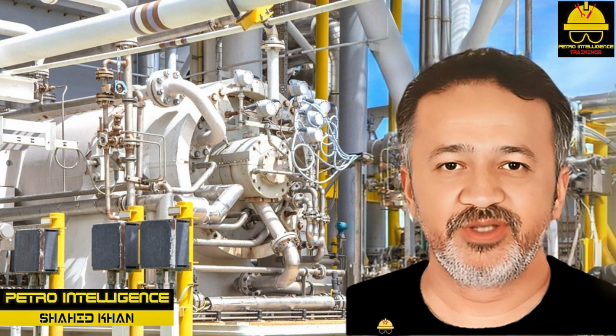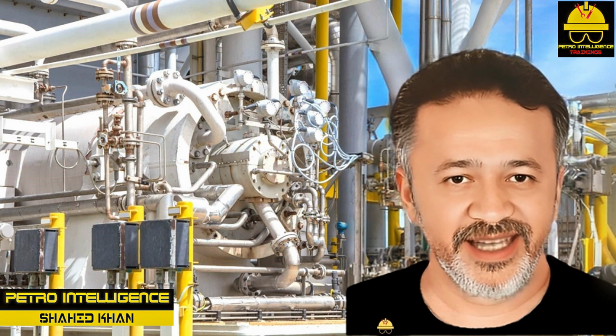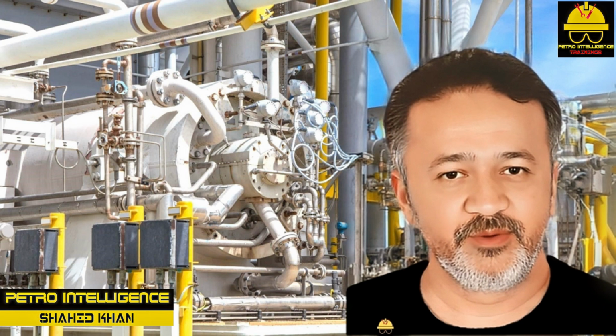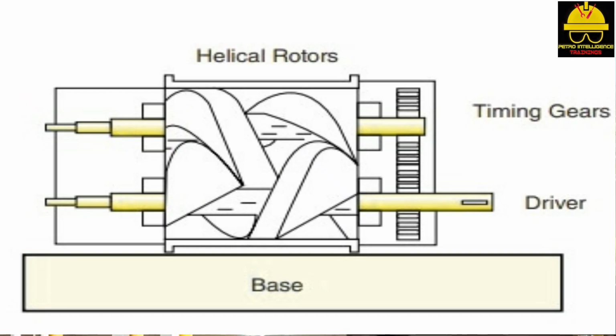Rotary screw compressors. The rotary screw compressor is commonly used in industry. This device closely resembles the lobe compressor and operates with 2 helical rotors that rotate toward each other, causing the teeth to mesh as shown in the picture. As the left rotor turns clockwise, the right rotor rotates counterclockwise, forcing gas to become trapped in the central cavity.